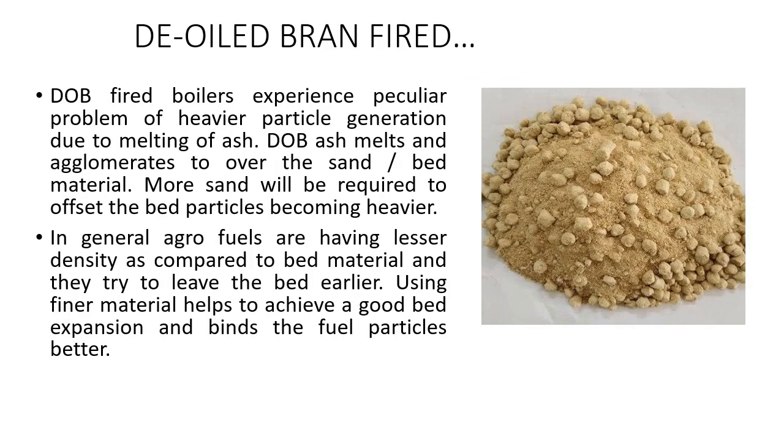In case of de-oiled bran fired boilers, they experience a peculiar problem of heavier particle generation due to melting of ash. De-oiled bran ash melts and agglomerates over the sand or the bed material. More sand will be required to offset the bed particles becoming heavier. In general, agrofuels are having lesser density as compared to the bed material and they try to leave the bed earlier. Using finer material helps to achieve a good bed expansion and binds the fuel particles better.